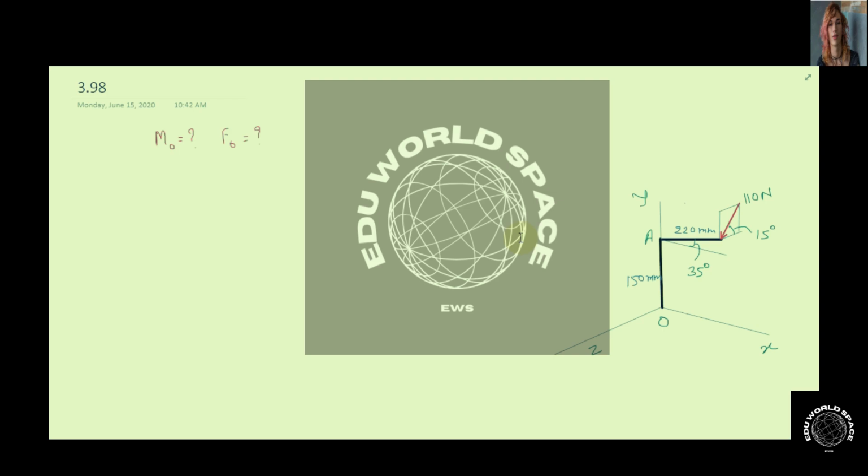Problem 3.98. In this problem, we have to find the equivalent force-couple system at point O. Here the force, let's say P, of magnitude 110 Newton, is acting at this edge. Let's say this edge is B. First of all, we have to find the equivalent moment at point O and the equivalent force at point O. For that, we have to resolve this force into its horizontal and vertical components.